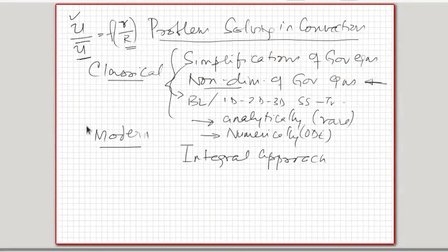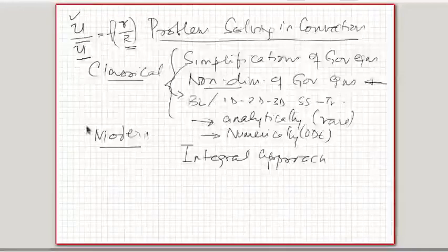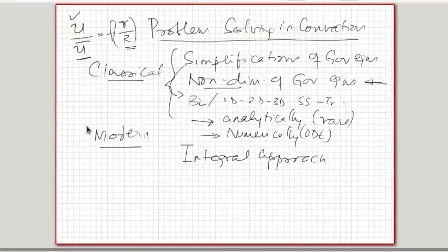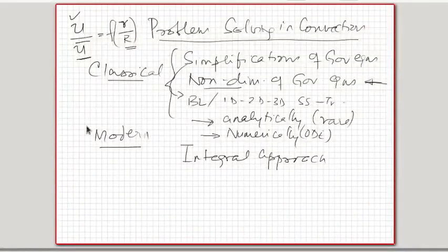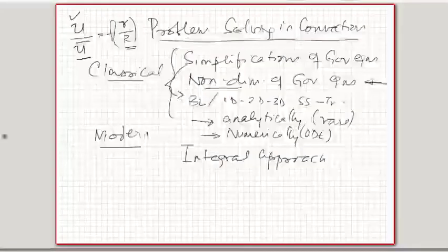So this gives you what is called an integral approach. You integrate the flow in the radial direction so as to get what is an ensemble of one cross section and use that which is varying with the axial direction. So the problem gets reduced in dimensionality to 1.